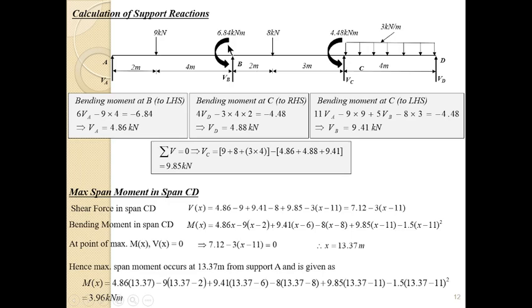The next moment is VB. VB will give a clockwise moment. That is why it is plus. Perpendicular distance here is what? Is 5. So you have plus 5. The next one is this 8 kilonewton load, and it's giving you an anti-clockwise moment. That's why it's minus. The perpendicular distance is 3. So you have this. Remember, you're taking moment from here. So equate it to the moment at D, which is minus 1.448. You will have two unknowns, but of course we know our VA.